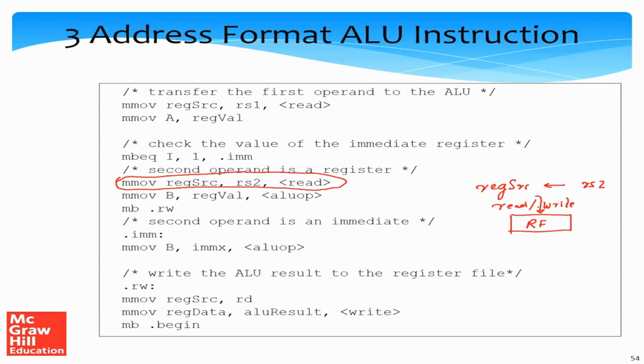Since a command is being sent, we'll activate the register file. And since it's a read operation, we will read the data from the reg source micro register. So we allow a concurrent writing of this micro register and also reading of its value. So we'll need to have a very small forwarding circuit. But that's a very simple detail. I'm ignoring that. But pretty much the reg source micro register needs to be accessed. We need to get its current contents. If its current contents are being written to, are being modified, that's okay. Whatever we are writing, we can sort of bypass the value. That's all right. And then we can start the access.